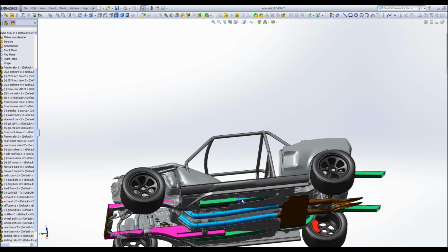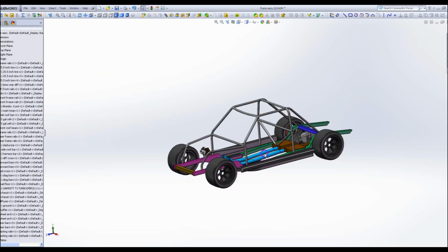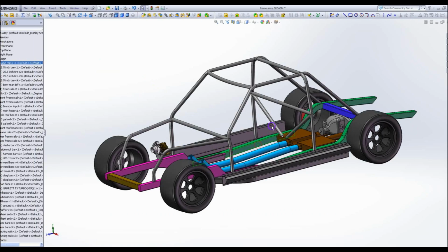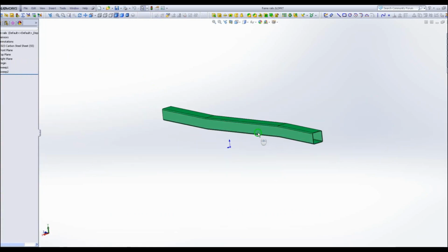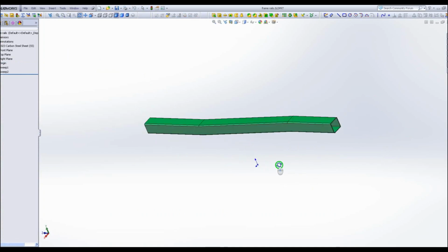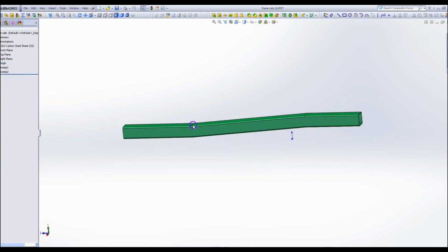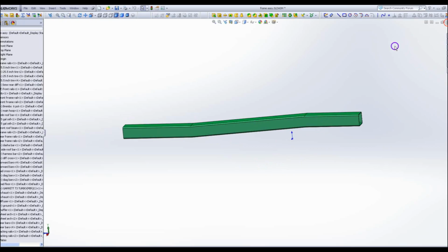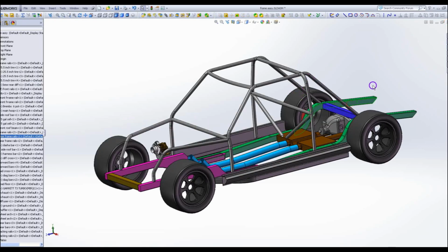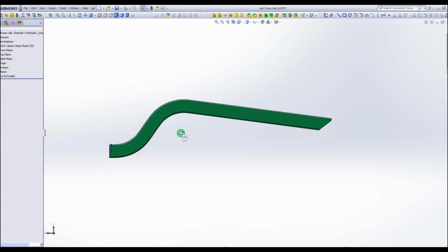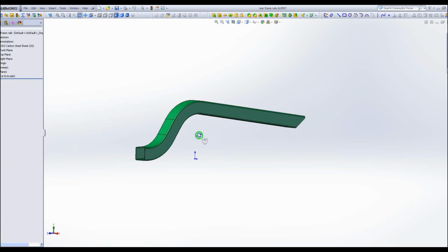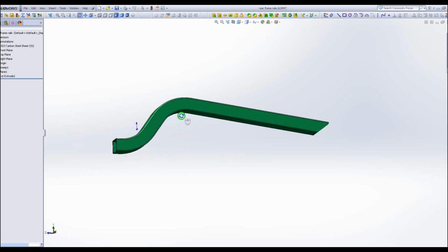The other thing that you should probably be aware of is this frame rail. Let's pop that open here. So the frame rail, this is made out of 3-inch square tube. I'll just pie cut it and weld it back together. So that's pretty easy. But these guys back here, the rear frame rails, are not bendable in my shop.